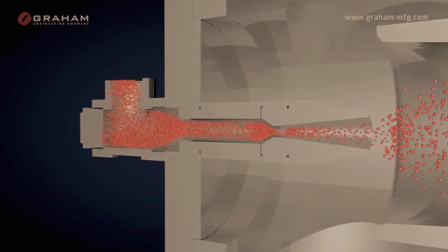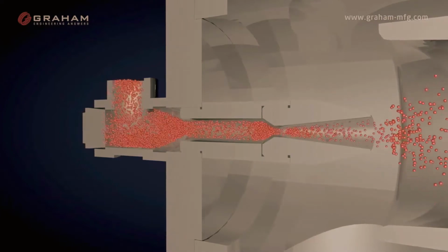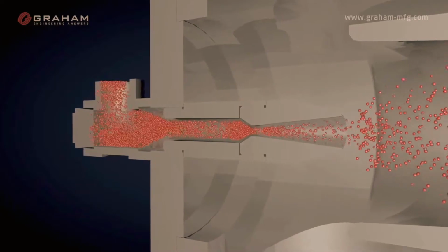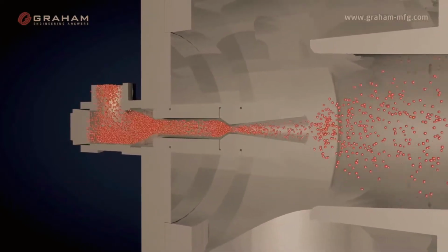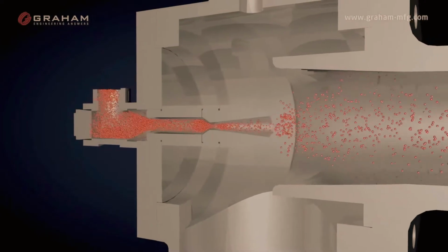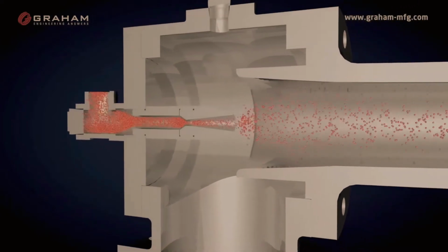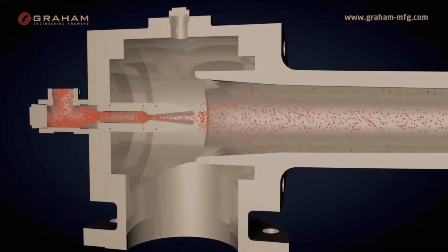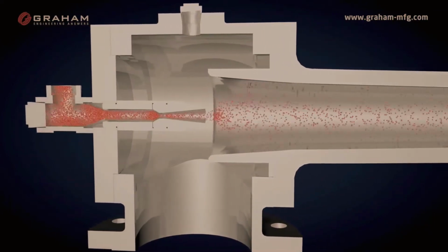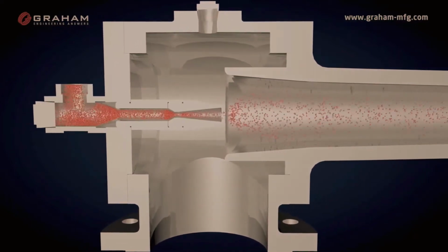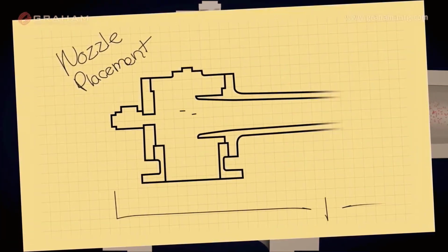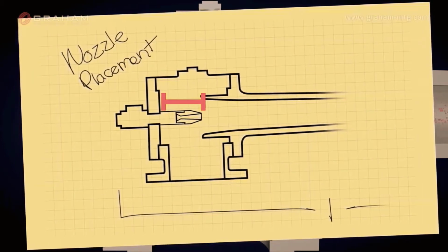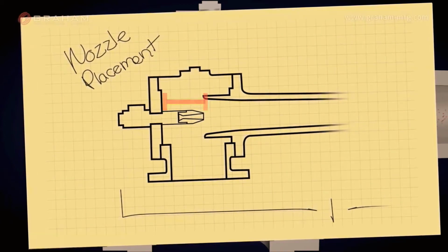The pressure differential across the motive nozzle accelerates the motive fluid as it rushes to the lower pressure region of the suction chamber. A well-designed converging-diverging nozzle efficiently converts high-pressure motive to a high-velocity stream leaving the divergent section of the nozzle. The motive gas actually expands to a pressure slightly less than the suction load pressure. That creates a localized low-pressure region, which draws in the suction load vapor. The design and location of the motive nozzle is set by the manufacturer for your specific operating conditions and plays an essential part in ejector performance.